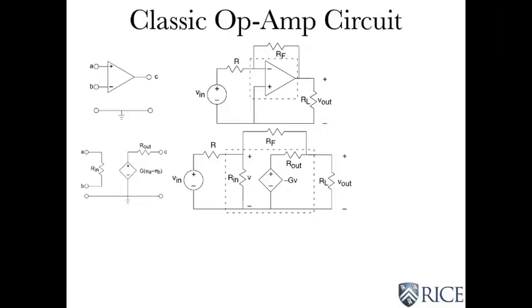Now, one thing to notice here is that the op-amp is put in upside down. So notice this is plus and minus up top. Notice here it's minus plus, and that's intentional. You'll see that in a second. Also, note that the plus side, node A, has been tied down to the reference. Okay? And node B is where the input voltage is coming in.